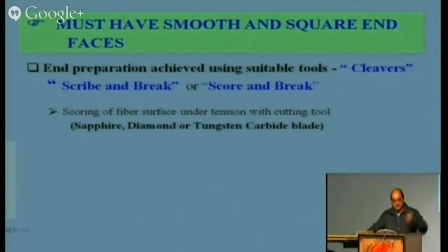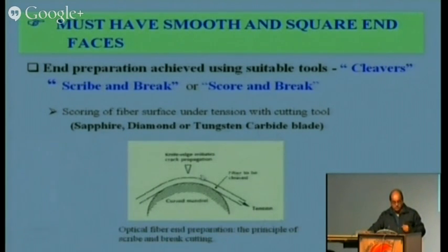So we can have this cutter. This is how you can put the fiber under certain tension, then apply the cutter and then apply the force at the two edges. So the crack will be, now the cut will be very fine. It needs practice. The skill will be tested on this part. So after practice, one can cut it very easily.